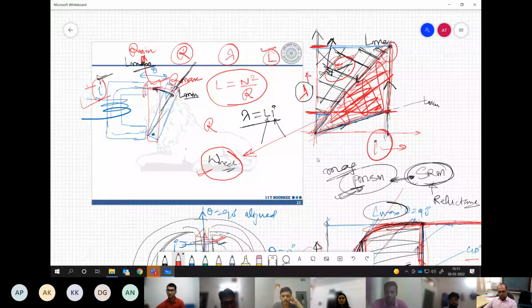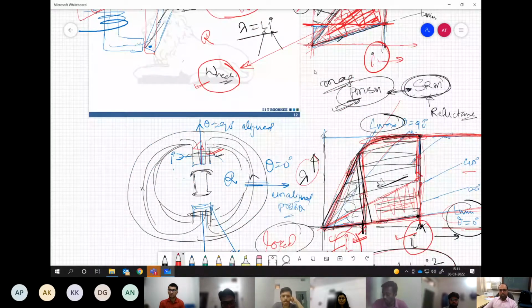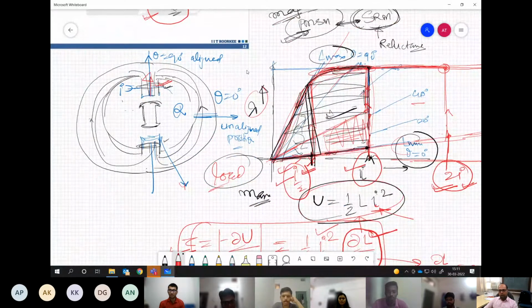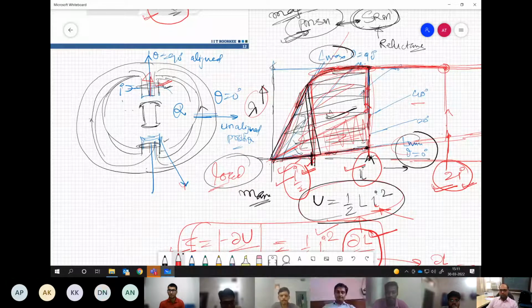So the same principle we have seen is used for the switched reluctance motor also, but we can utilize the core better if we go up to the saturation limit of the core. So this is better utilization we are making. Of course, we have a bigger area which is coming as the mechanical work done.